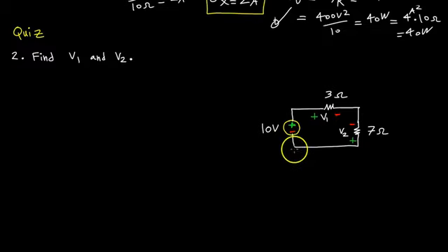the standard thing. So I'm going to start here. I'm seeing a loop here, and there's the same current flowing through everything, so I'm not going to apply KCL. I would only apply that if I have multiple branches that are in parallel and not in series. Since I have the same current I, I'm going to go ahead and use KVL because I'm interested in finding the voltages. So I'm going to start from this point and go clockwise.